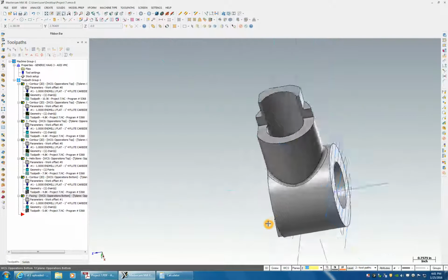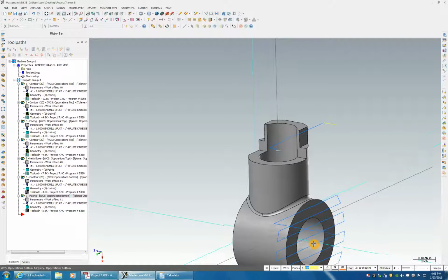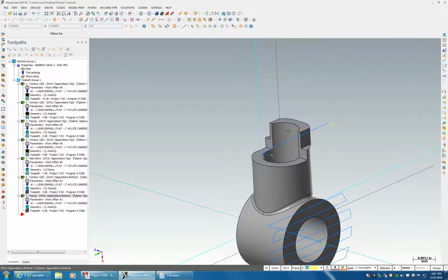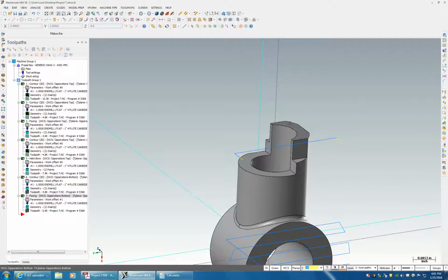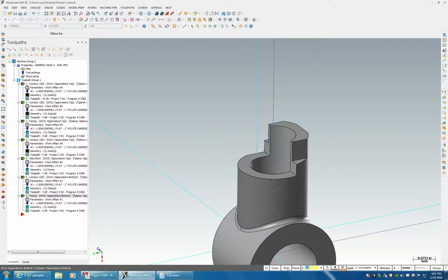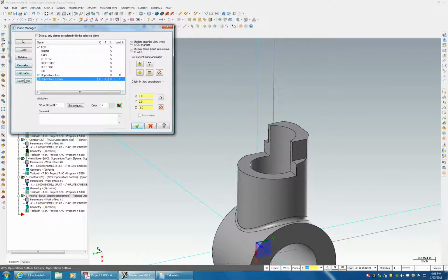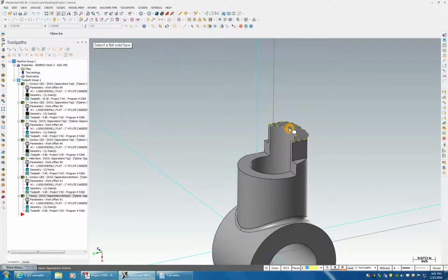Now, I'm going to say we're going to have some kind of fixture where we'll put it here. This time it's standing up like this. This time I'm going to put the origin right in the middle of this. How would we do that? I'm going to use this machined feature here, and right smack dab in the middle is our WCS. And turn off all our tool planes. So let's go WCS, plane manager. We'll do a solid face, and this time we'll select this one.